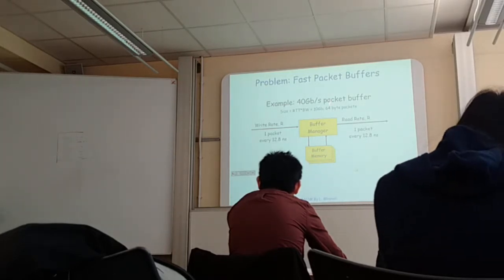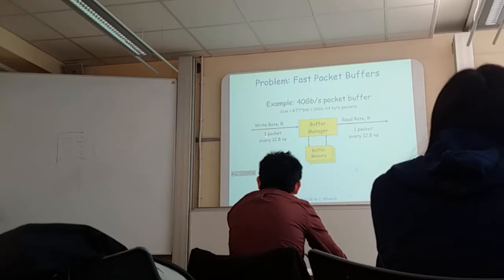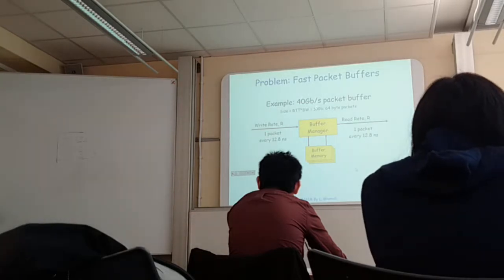Now, if we assume that we have 64-byte packets, at this speed, you will have a packet coming at that bandwidth. Each packet is of that size, so this buffer will have to write packets at this rate.